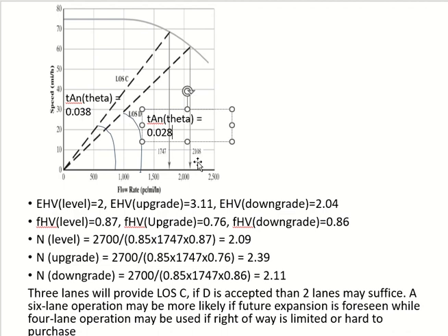You will still have the level of service. Somebody may say, but D is also acceptable. Why don't I put 2 here? So instead of C, I will get D, which is also acceptable. But again, the same thing. D is acceptable right now, but maybe in future something unexpected happens, traffic is more, you will not even have D. So we will give 3 lanes. Okay, got it?